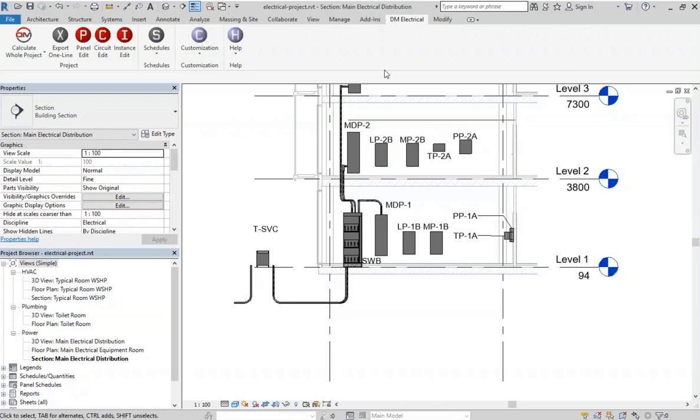No one that we have run into yet says that they actually use the feeder sizes in Revit. And if you don't have a feeder size, you can't do anything. So we took out their feeder sizing, put in our own, and then once you have feeder sizing, you can do fun stuff like voltage drop, and fault calcs, and arc flash calculations.